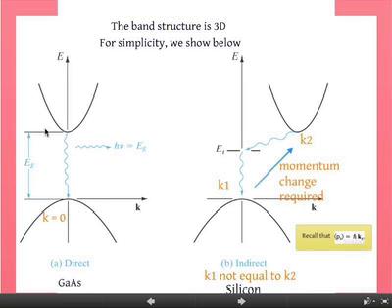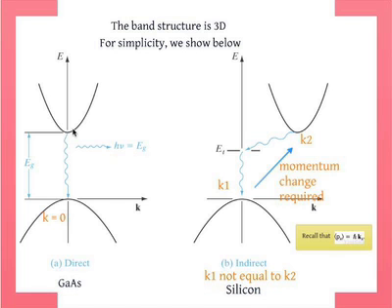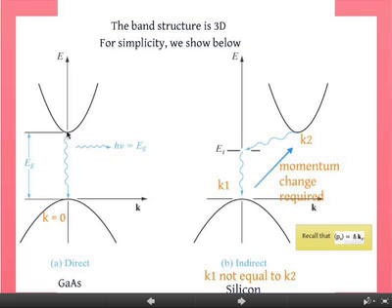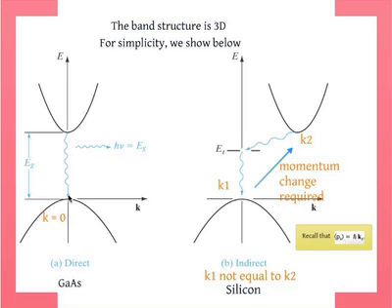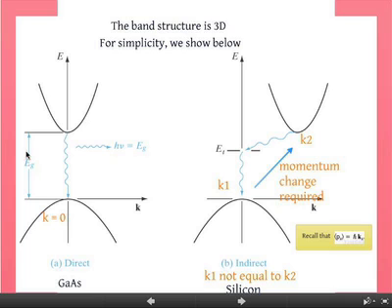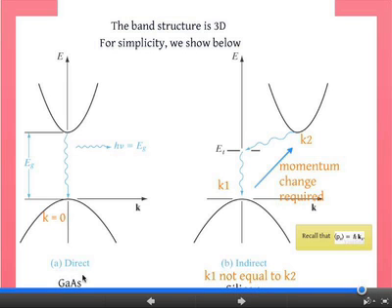Okay, a few other things to keep in mind, and we'll come back to that, so don't worry too much, is that this is the band gap. So remember, the band gap is defined as the difference in energy between the lowest energy level of the conduction band and the highest energy level of the valence band. Because they have shapes, you can have different values, right? They're not constant. So keep that in mind. So that's the band gap, Eg. Okay? So that's gallium arsenide.